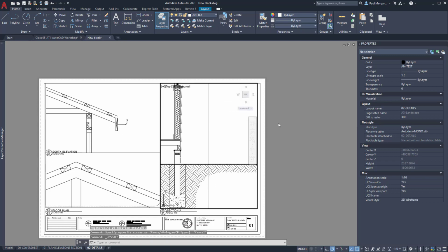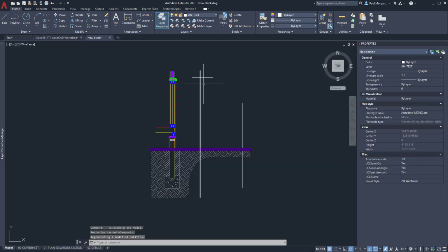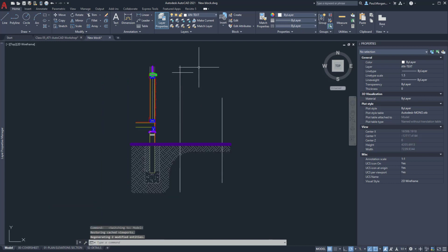Double click into the space, into the drawing space, and I'm going to draw another line from, say, just here, and go straight up to, say, somewhere around there. Hit escape so I can see that line there, and that will be fine. I think the other thing I need to do is maybe just draw one up here somewhere like that. Hit escape, get out of model space, go back to my model, and then I can see those lines here.